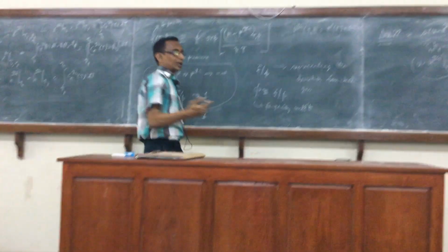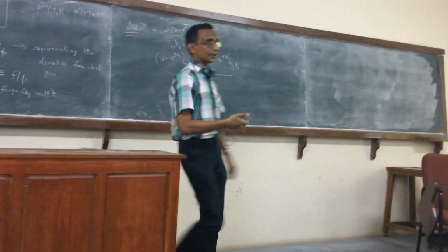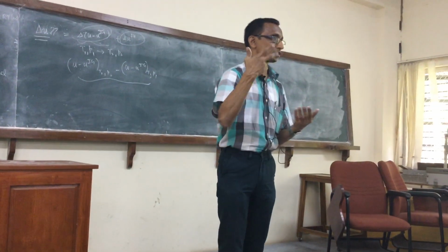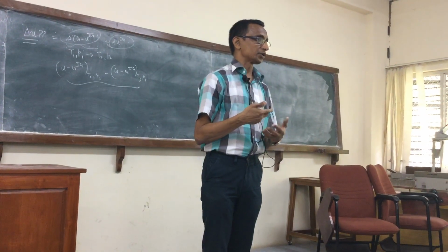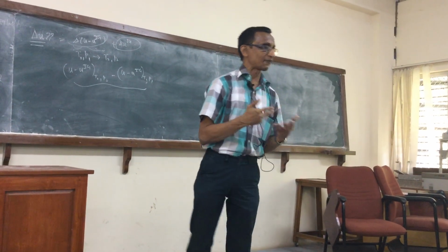Now of course if the specific heats, let's say over the temperature range, are not varying that much, then we can replace it by some average specific heat, right, and I can write this as some average Cp times (T2 minus T1).